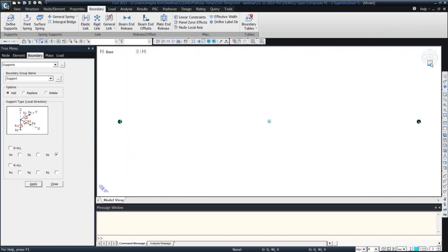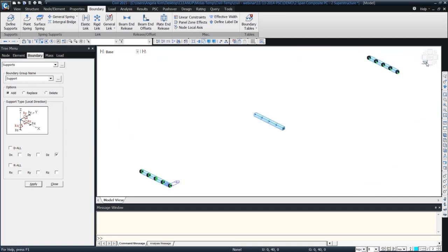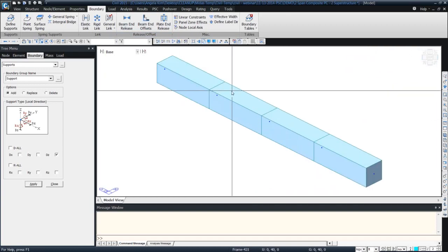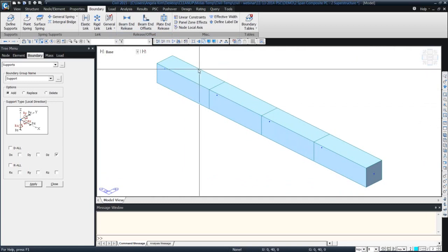Okay, so now I'm going to work on the middle portion. And this icon over here is to control the view. So you can actually have the ISO view at different angles. Plan view, cross-section view, or side view, whichever view you need, you can always get that utilizing this guy over here. I'm going to activate the middle portion so we can concentrate on modeling here. So basically, for the ones who are new to Midas Civil, I activated this portion using a feature called Activate here.